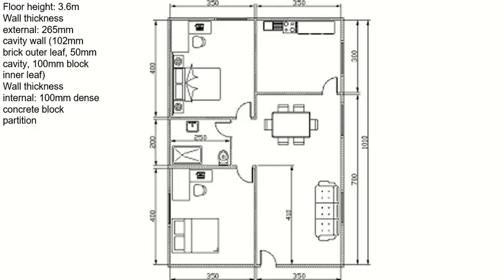Okay, this is the plan which we will try to do now. We have the whole plot, and then there are rooms given as well, and these walls are different. The external and the internal walls are different, so you have to calculate them separately. First of all, all dimensions are internal dimensions, and the thickness you will take from the text. The height of the floor and the thickness of the wall are given in the text.